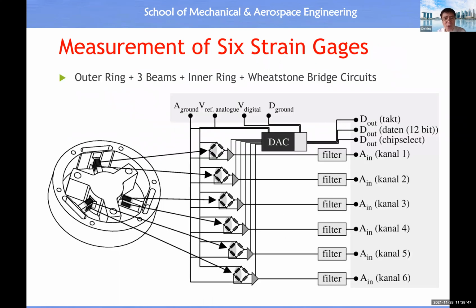All right. So in the video, you have seen the design which makes use of 3 pins to connect the inner body to the outer body, and assume on each pin we only have 1 pair of strain gauge. Therefore, we only have 6 readings, because for each strain gauge we must use its own Wheatstone bridge circuit.